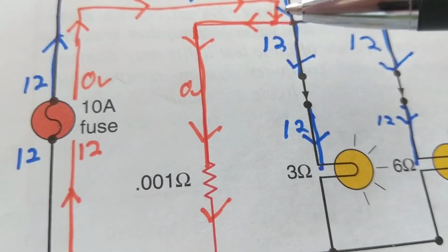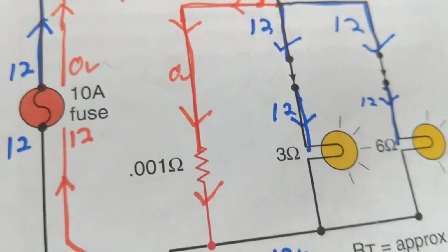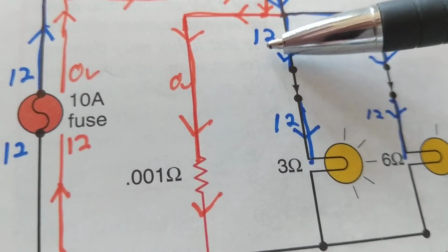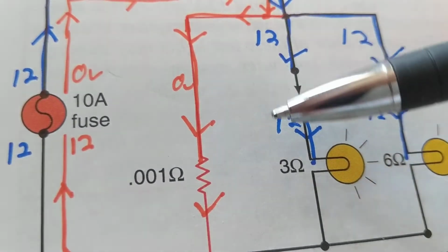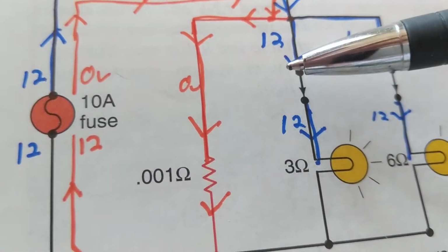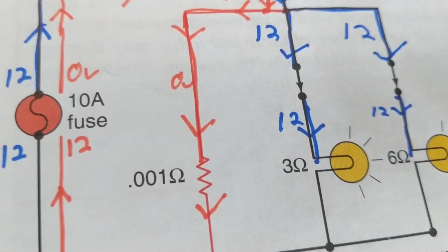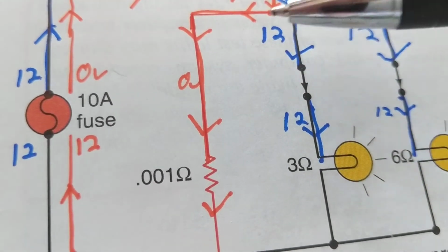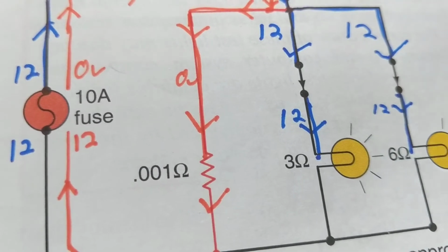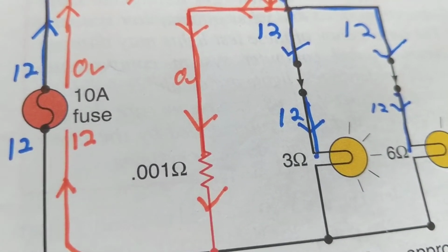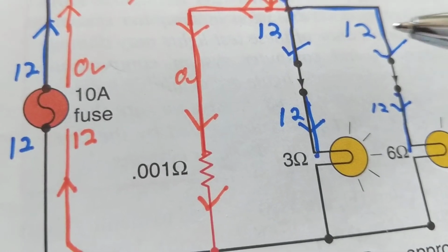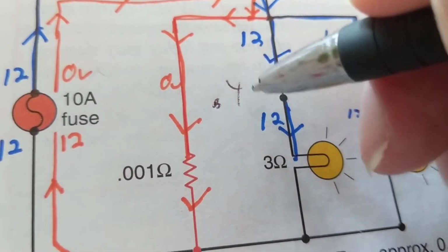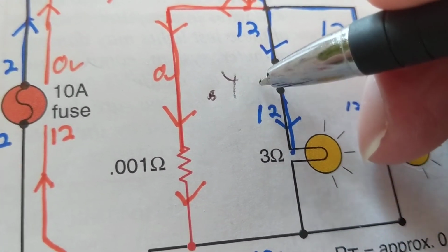If you do not adjust it accurately, this being the reference voltage for the TPS for the computer, you will have hesitation problems accelerating. You might even stumble before you accelerate. You might even lock up. This controls the air-fuel ratio. If it doesn't see enough air because the throttle position sensor is not adjusted right, guess what? Less air, less fuel. So you press the pedal, you have a hesitation, eventually it'll figure it out and give you the fuel. But if it's 0.4, it opens the throttle, right?